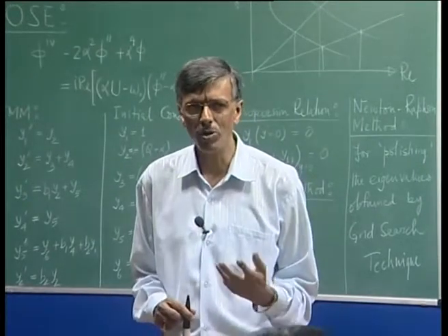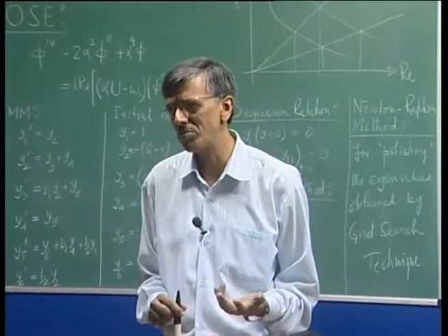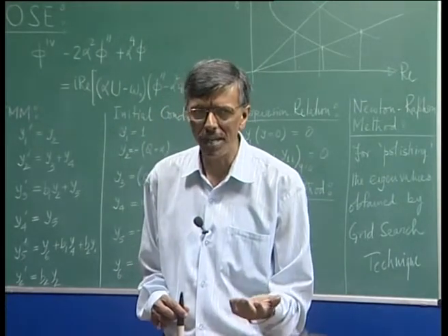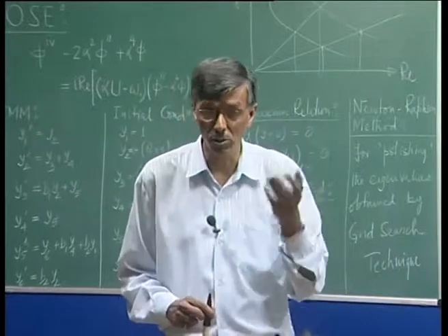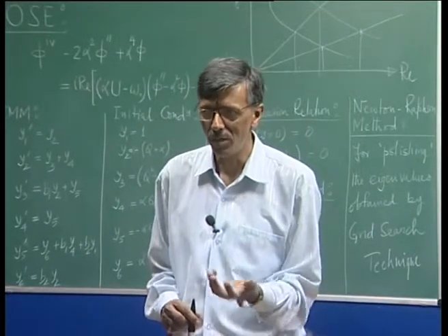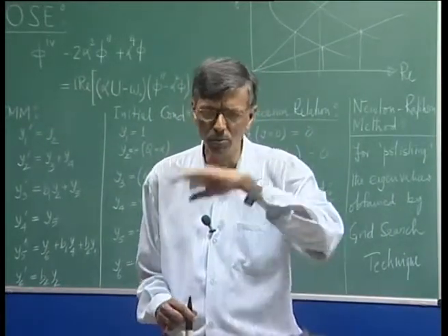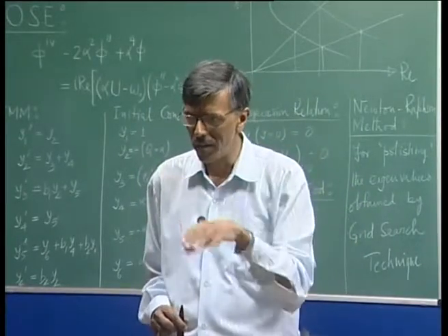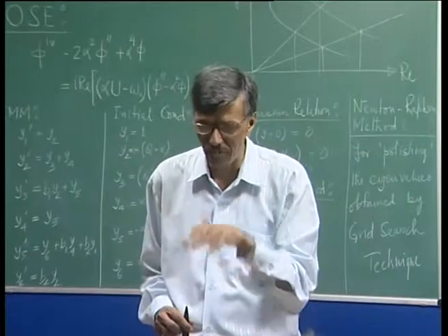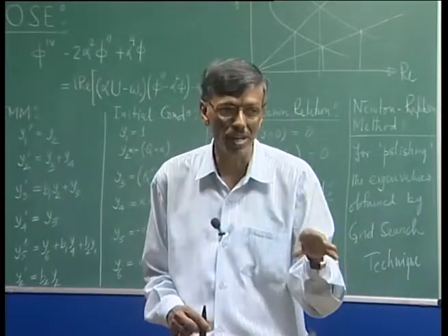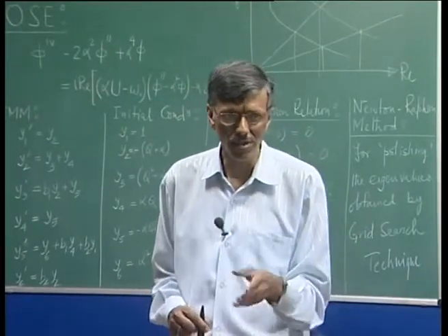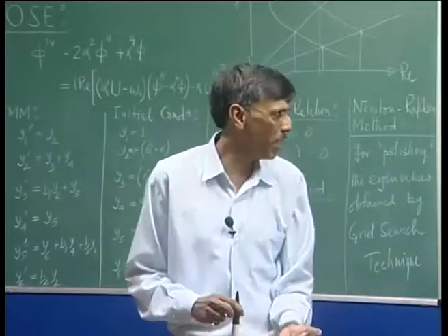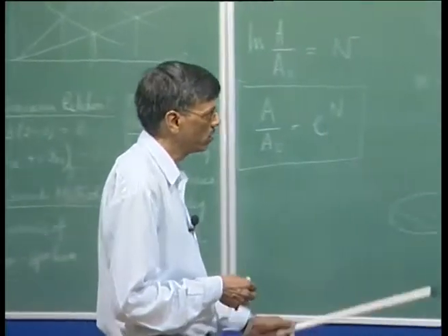One talks about displacement. What does displacement mean? It is as if a streamline has been displaced by that amount due to the viscous action. Because what happens? Ideally, outside the shear layer we would see the inviscid streamline, but as we come closer to the surface, it has to adjust itself so that you satisfy the no slip condition. So, this is equivalent to as if the whole flow has been lifted up, displaced. That is what is given there.